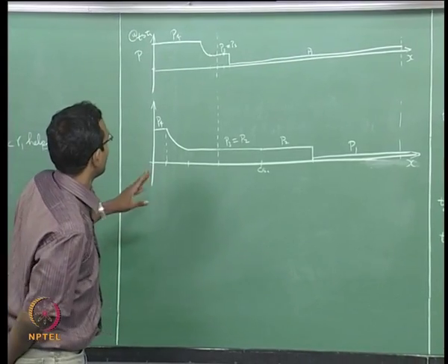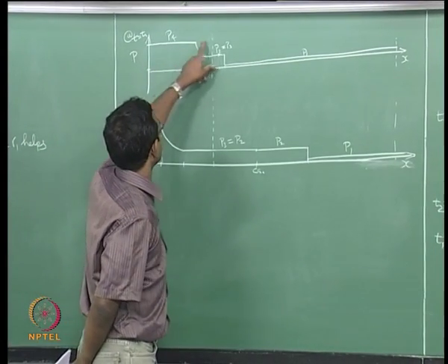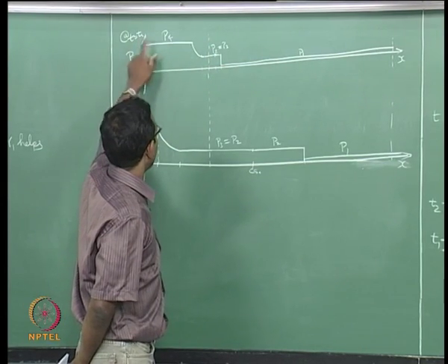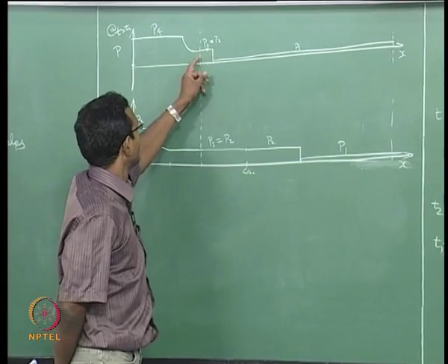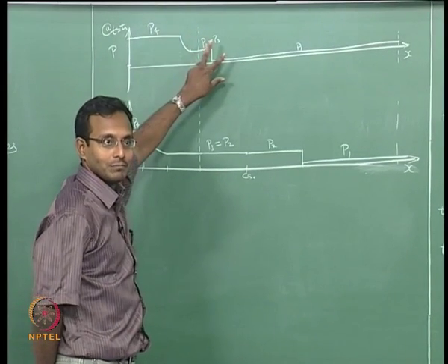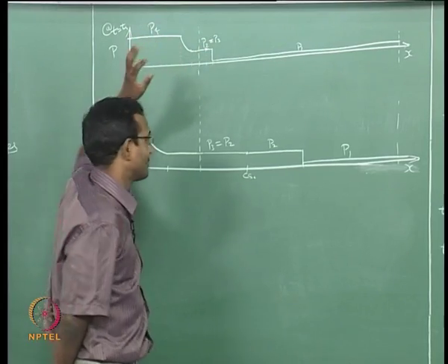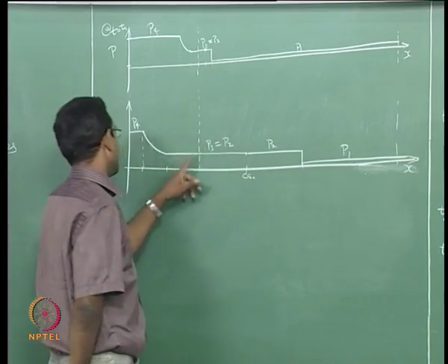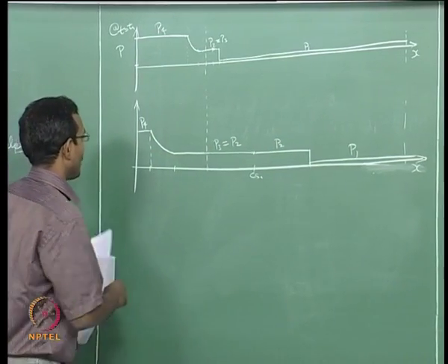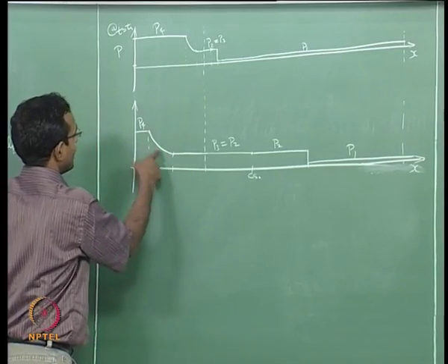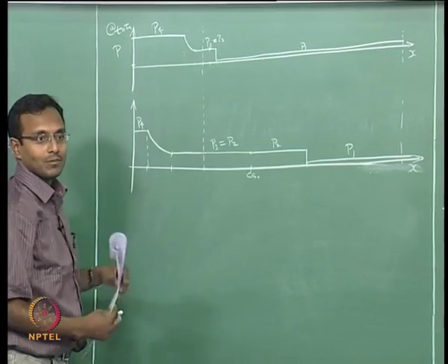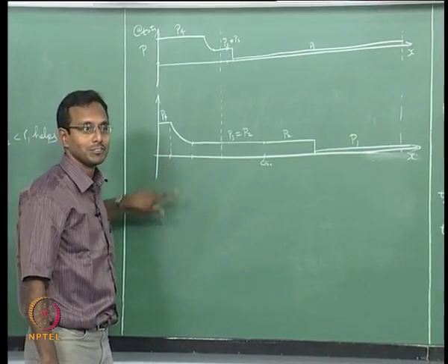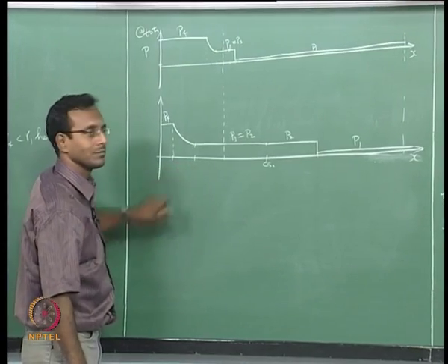What is happening is, there was the initial condition, what was it? It was a sudden step from P4 to P1 at time t equal to 0. After some time this has developed a shock and the pressure is something in between P4 and P1. It is trying to come to some equilibrium between these values. It is coming to something in the middle, and then this whole region is becoming that value, and on this side it is going this way, and you can notice that this curve is now less steep compared to the previous one. Why? The expansion waves in the expansion fan are going apart from each other, so they are going to split out slowly like this.